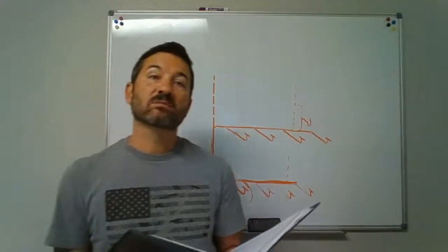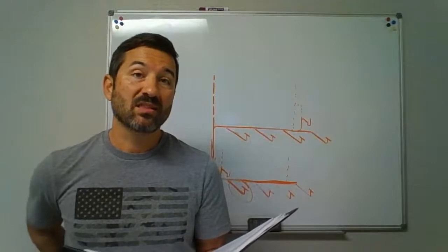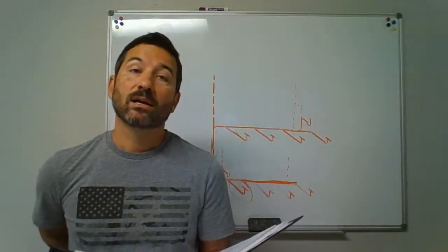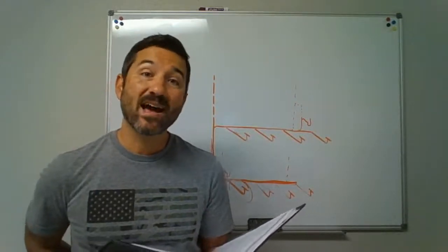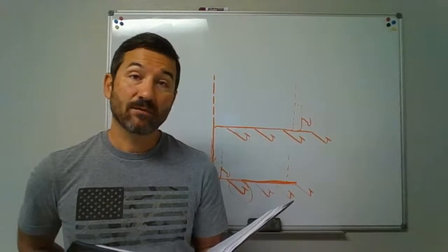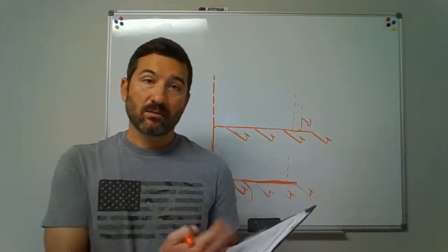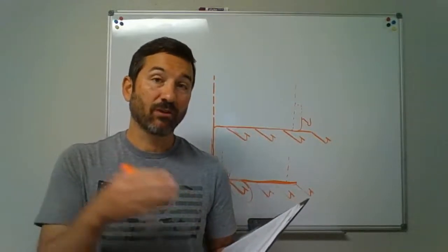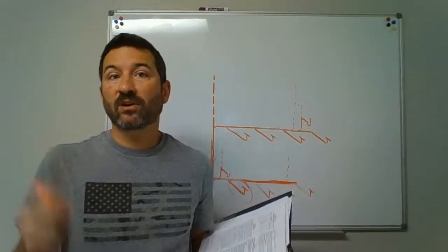Combination waste and vent systems, like I spent a lot of time on, do have to be approved. So you're normally going to see that in a commercial plan, and that has already got its plan approval. So if you had a floor drain that's sitting way out in the middle of the floor, and you say, I can't get a vent up on that thing. It's already told me that there's a maximum distance I can put this vent from that drain. There's no walls for me to pull up a vent. How can I do it?